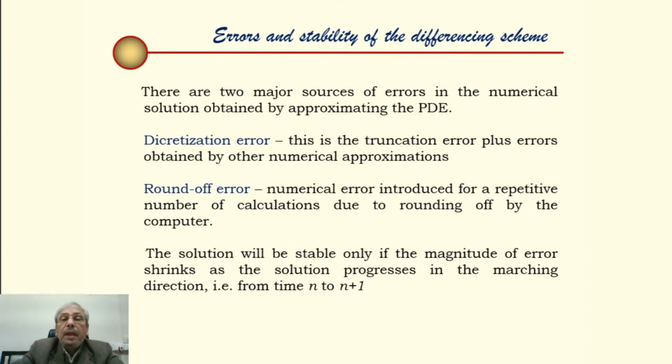Now we will mention a topic which is related to explicit schemes, because we are not adhering to only one type of scheme, implicit or Crank-Nicholson implicit. In some places we will see explicit schemes are more advantageous. But for explicit schemes, we have to pay attention to a major factor, which is basically stability.